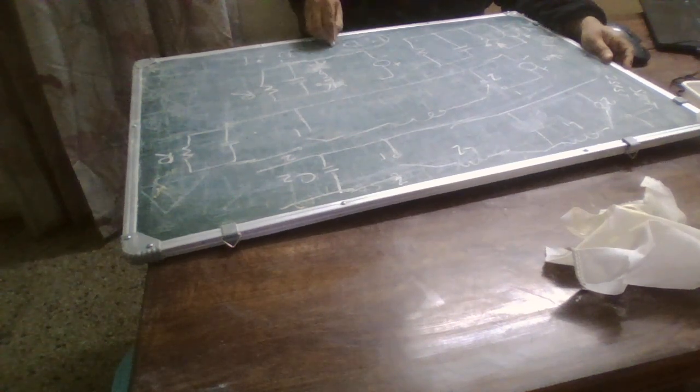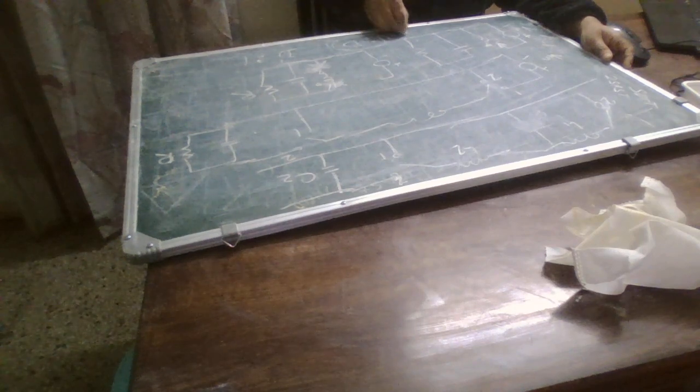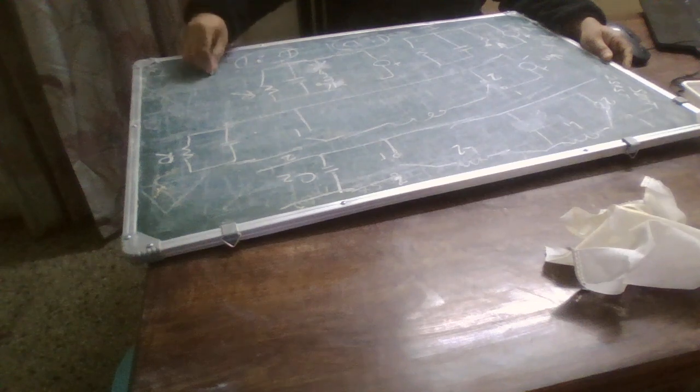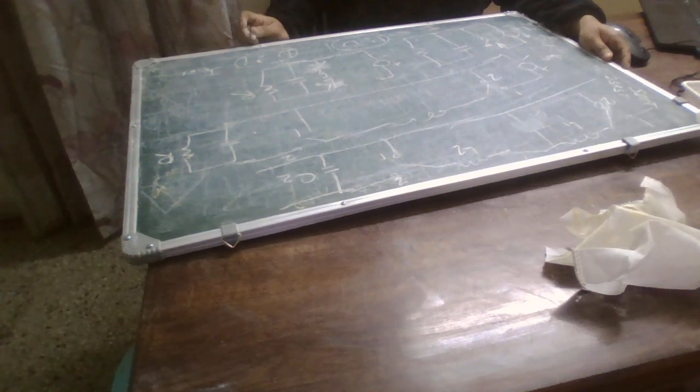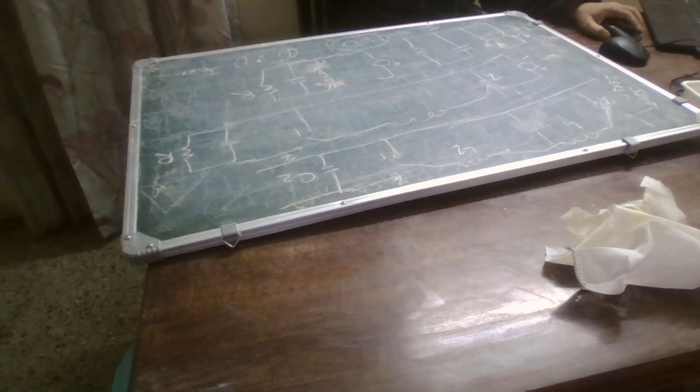So this circuit is going to inherit the properties of both. What property is it having? Both are having a pulsating current property. The difference is that here the pulsating current is the input current, and here the pulsating current is the output current. So it's going to get the properties of both of these, and this basically finishes our derivation of the circuit configuration of a buck boost.